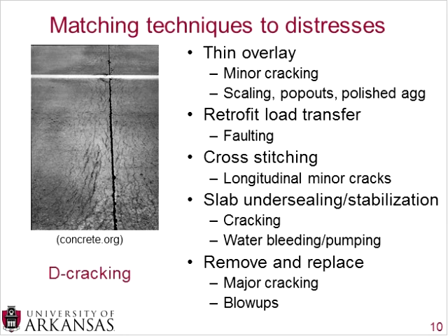And then finally, removing and replacing. This takes care of major cracking and also blow-ups. So if you have major cracking or blow-ups, sometimes the best option is to simply remove the material and replace it. And that will be the best way to match your technique to your distress.